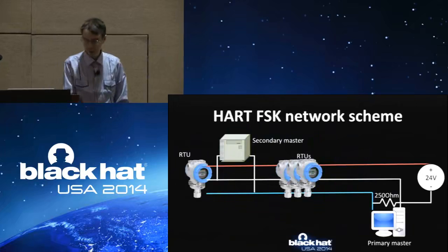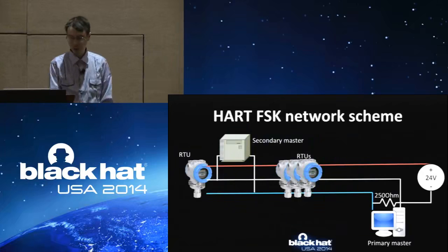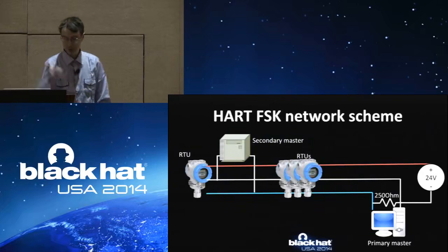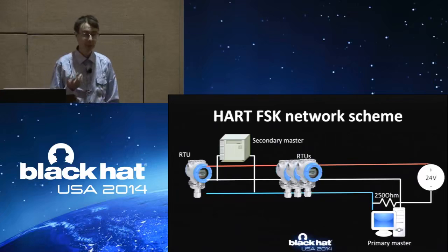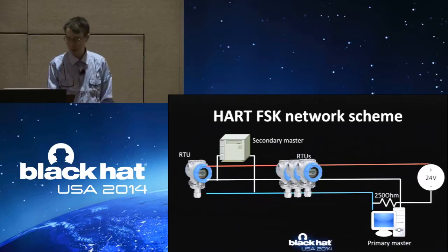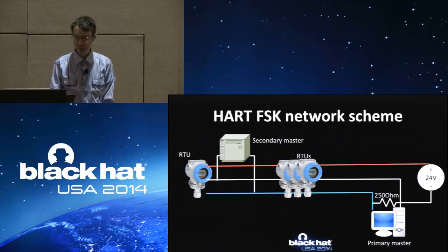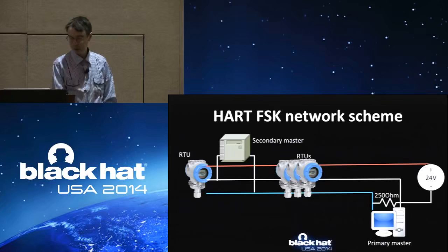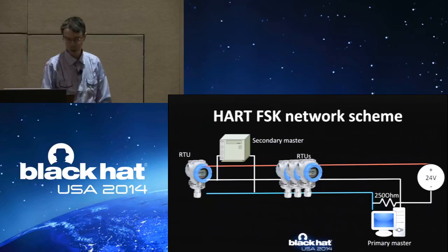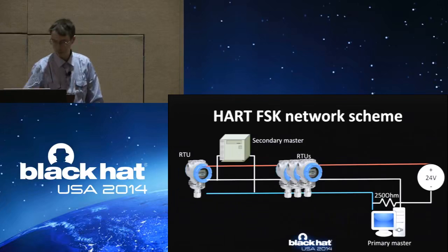An example HART network scheme is shown here. For creating a current loop communication line, you just need 2 copper wires. In reality, it's also the same. And as I've said earlier, the length of these wires could be up to 3 kilometers. Also, many transmitters could use the same wires for power and for communications.